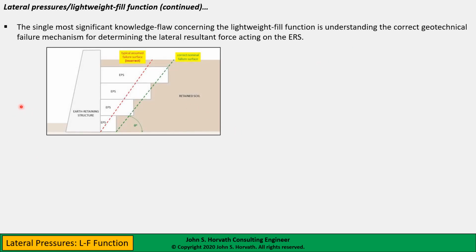Looking at the more widely used, more widely known full depth application, we see the stair step of EPS blocks. Still to the present, there are far too many people who just assume that somehow a failure surface magically develops through the EPS blocks, identical to the Coulomb type plane that is assumed to develop if this were all soil.